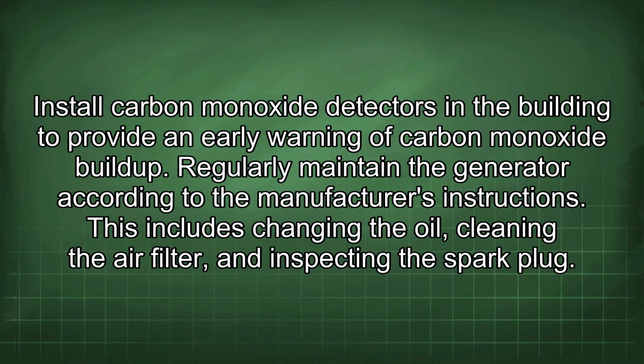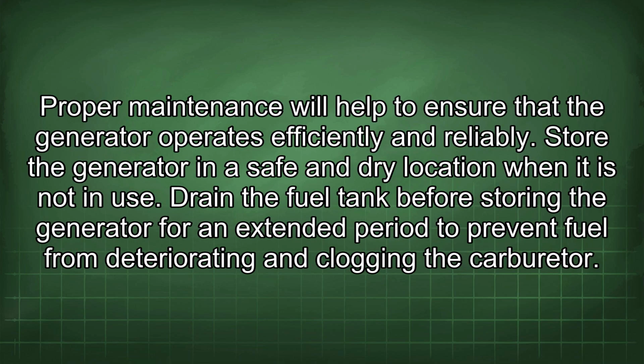Regularly maintain the generator according to the manufacturer's instructions. This includes changing the oil, cleaning the air filter, and inspecting the spark plug. Proper maintenance will help to ensure that the generator operates efficiently and reliably. Store the generator in a safe and dry location when it is not in use.